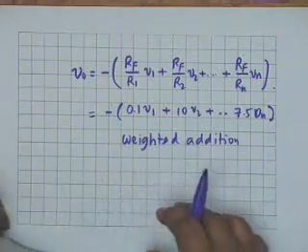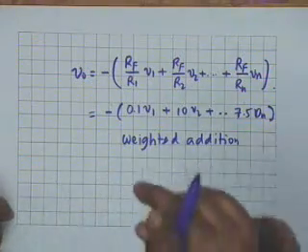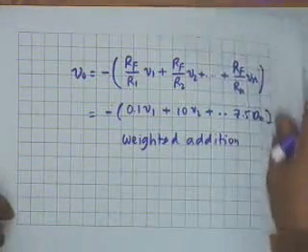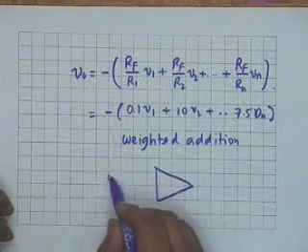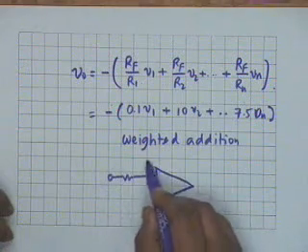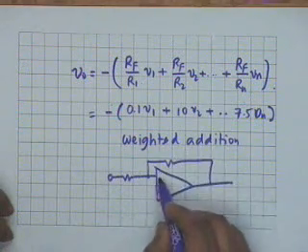What you can do is, let us find an alternative solution first. Suppose I am stuck with this. Let us say I have a chip which does this, and I want to use this chip. There is a negative sign. I want to change the sign. What do I do? That is correct. You take an op-amp with a -1 gain, which is simply this op-amp.